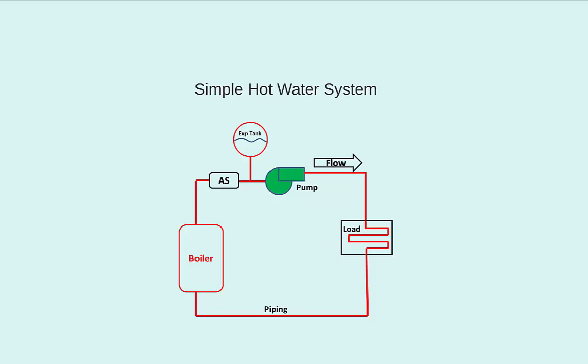The process of evaporation and then collapsing is referred to as cavitation, and it can be very damaging to pumps. It's like mini implosions occurring inside the pump. These implosions emit high-intensity shock waves, and such shock waves can damage components of a pump, in particular the pump's impeller. Thus, we always want to ensure a significant amount of pressure on the suction side of the pump is present, since it's harder to evaporate water at higher pressures.